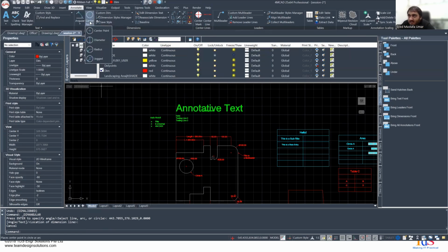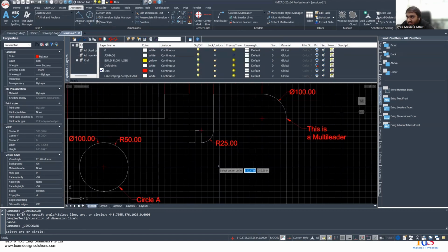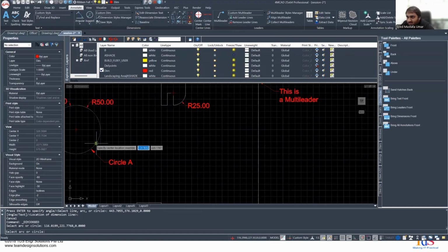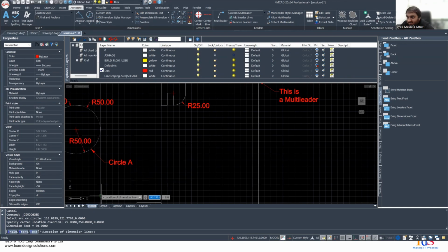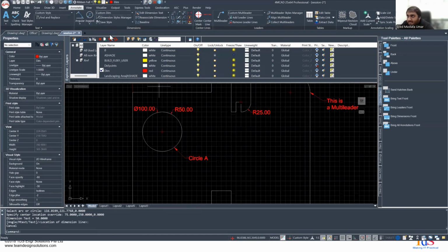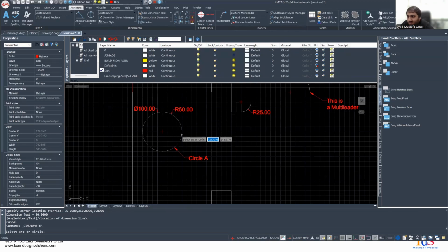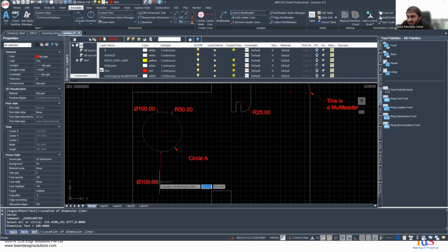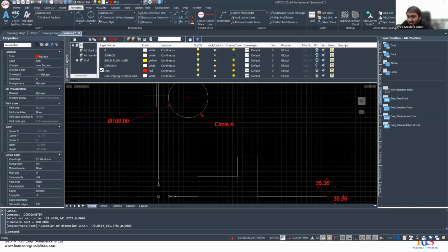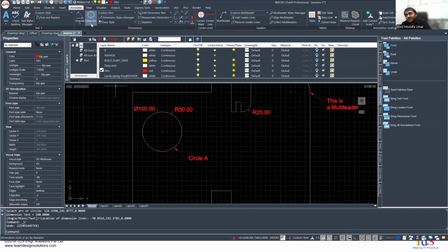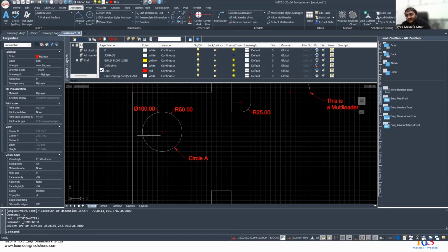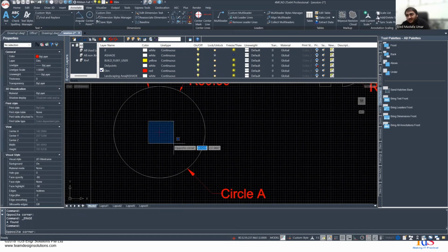Let's keep these three in mind. And then this is an important one as well, where this allows you to specify the diameter, the radius, as well as the center point, which often you probably won't be using because it looks very weird. But the idea is that these are the main ones of use, and to do that, you can simply select any circle, and it will start showing you this sort of arrow for the diameter, for the radius, and then for the center point, you can just select a circle, and it will add a center point to that circle.